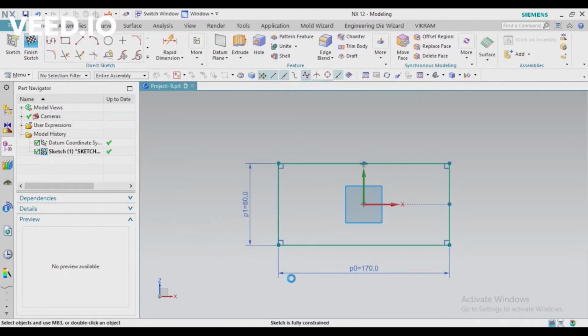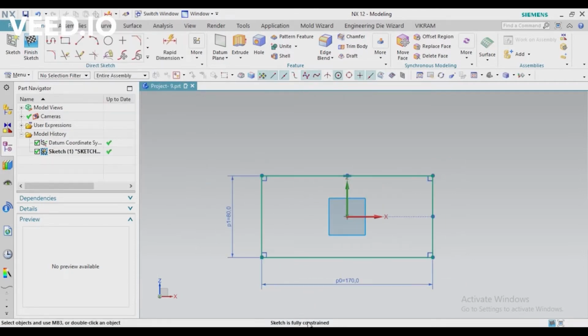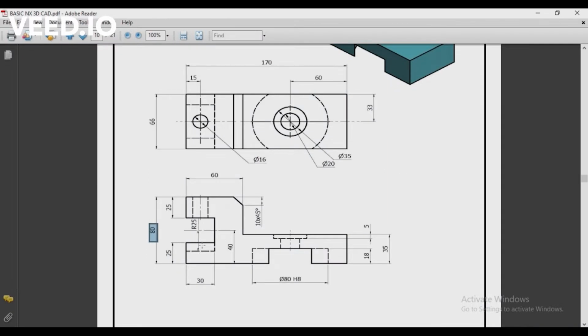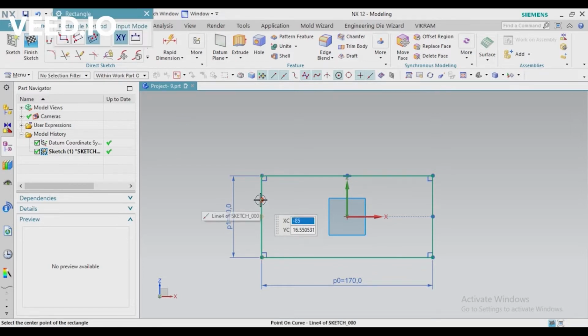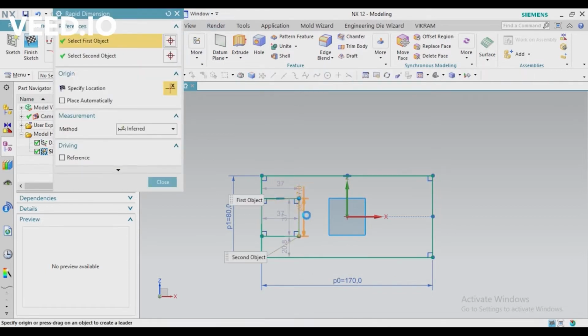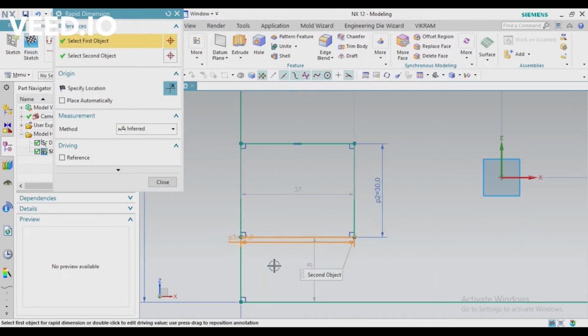Okay, so actually we don't need this closed area, we need another area. We are going to remove this cross section inside. You can see what area we actually have to remove. Many dimensions are given for that, you can calculate. For the inside rectangle size, select corner rectangle, and first define this rectangle's height as 30 mm, and the length also 30 mm.